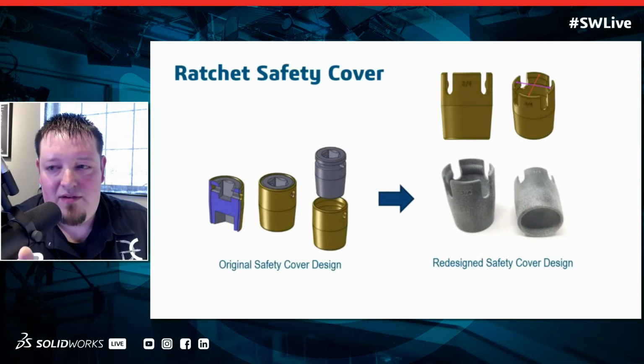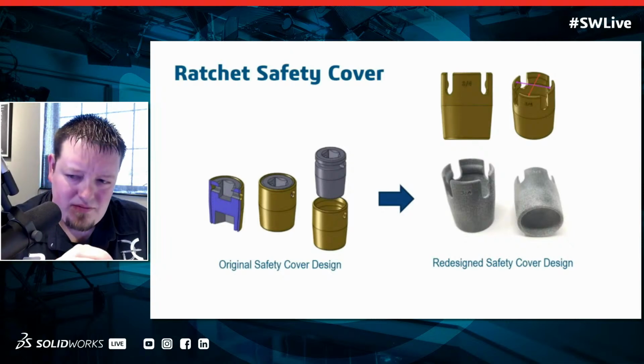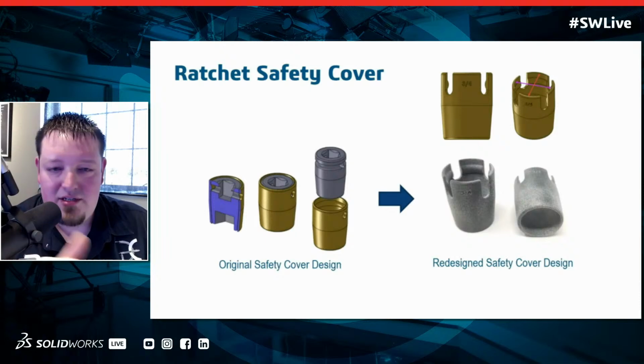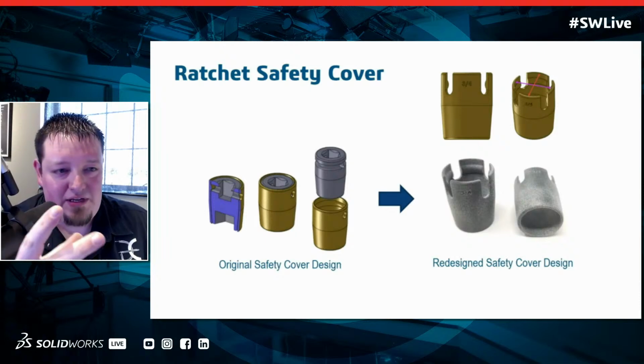This would be something that would be very costly to do with CNC. But here, if there's one thing that people remember from today, and it's the only thing they remember, it's that with additive manufacturing, size will cost you, but complexity is free. So text, texture, crazy features, non-machinable features, non-moldable features, they don't cost you anything extra. It's when you try and go, oh, I want to print the entire door to a car, that is going to be very expensive. But for little guys like these, they're only this tall, put as much complexity in as you want, because you're going to be ordering 50 of them. Each one is going to be different from the next. It doesn't cost you any extra for that complexity.